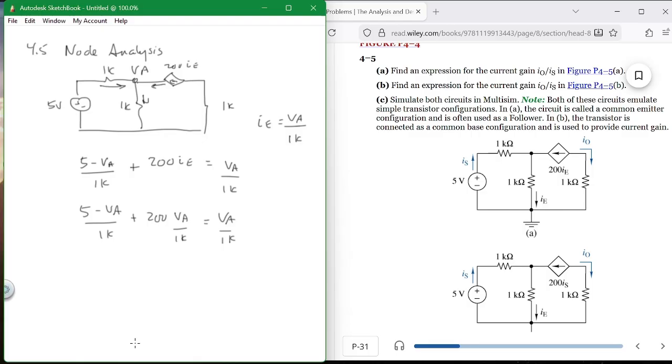I use node and mesh analysis as equal partners, and sometimes one gets it, sometimes the other gets it. Usually 9 times out of 10, mesh will get it. That's why I went to mesh first, even though I knew it last night that no, this is a node analysis problem. Now, I rewrote it and I got it because I can use current. So you use whatever is available. You take advantage of whatever they give you. And in this case, it's node. All right?